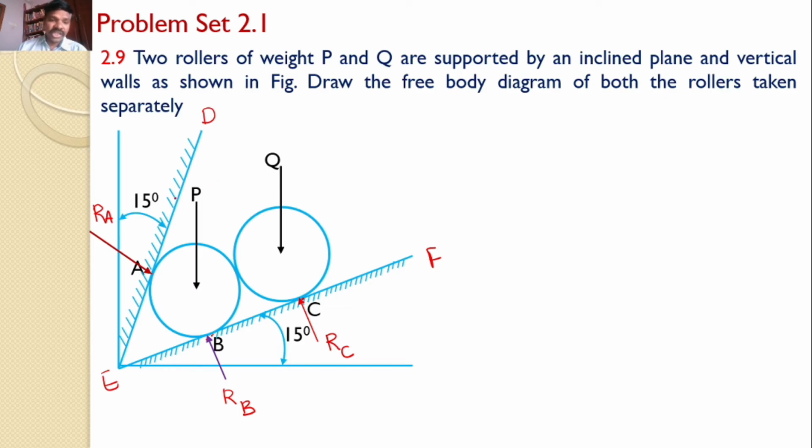Just by extending the same concept of these fixed support reactions, here also the reaction force will be perpendicular to the supporting surface. What is the supporting surface here? So to draw the perpendiculars, let us draw a tangent to this. Perpendicular to this tangent, along the perpendicular to this tangent, the reaction force will develop.